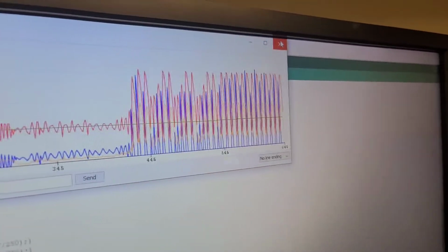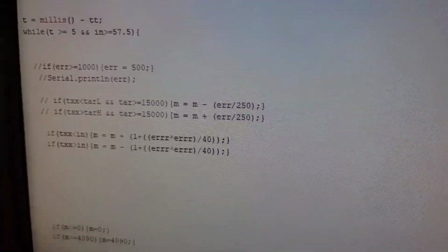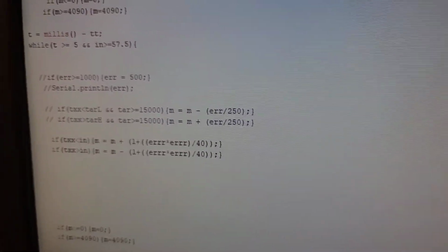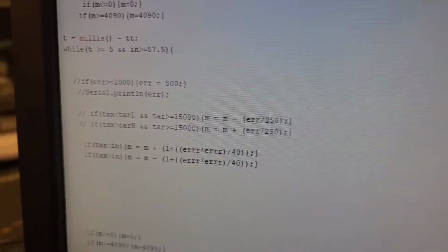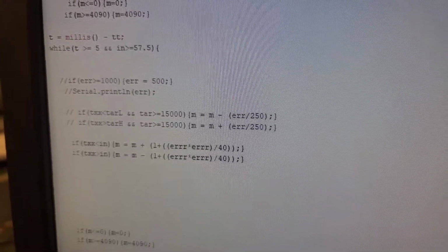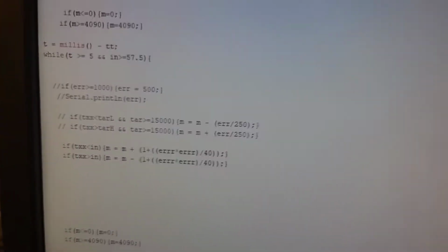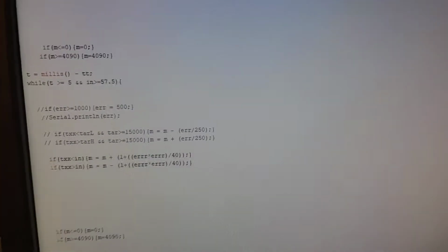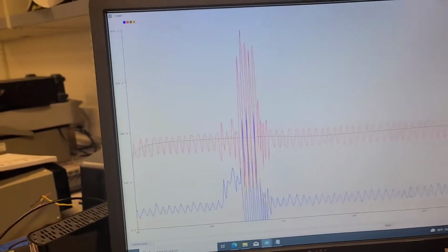I gotta stop that. Those oscillations are coming from me squaring the error, so as the error gets really big, that's the amount we change the driving M magnitude by, and it's squared. So, if the wheel is spinning twice as slow as where I want it to spin, it will have 4 times the push, as if it was spinning like, I think 1/2 as slow, something like that. But I moved the damping up to 40, so. See, it's actually pretty stable.